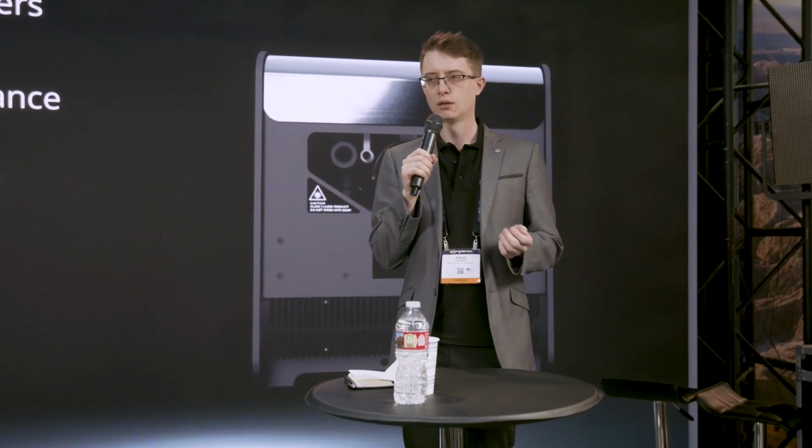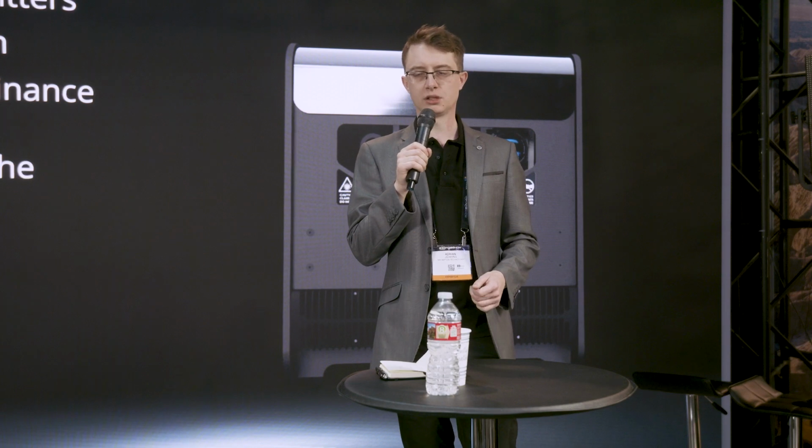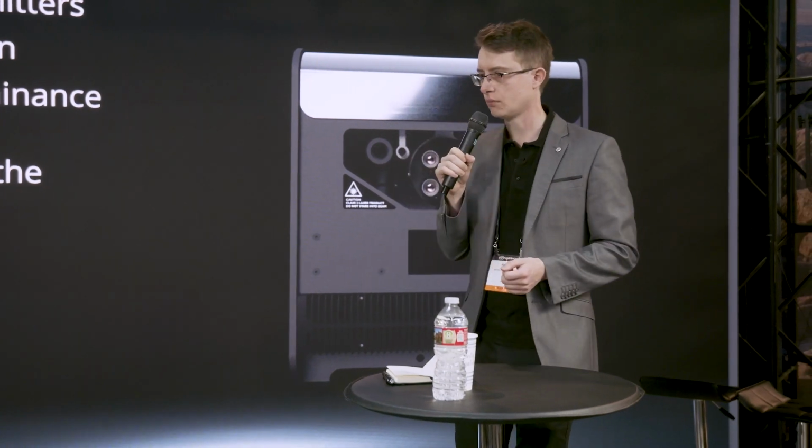At Brompton, we've been talking about RGBW. But for us, the W doesn't stand for white. It stands for whatever. We're able to cope with any fourth emitter, both in and out of the gamut. So that could be a warm white, as in the panel we've seen today, or it could be a gamut extending cyan, a cool white, an amber, or basically anything you like, depending on what you're trying to achieve. The calibration system deals with this entirely. There are no firmware updates to deal with different emitters. It's completely a calibration problem.